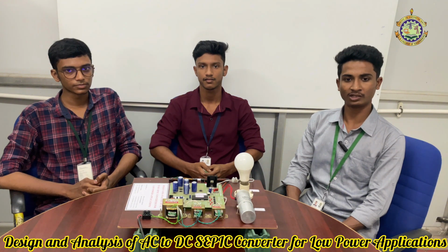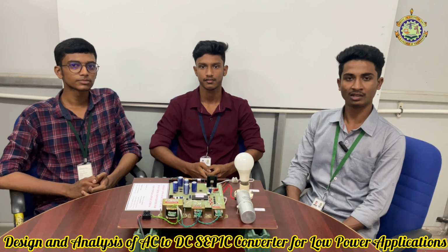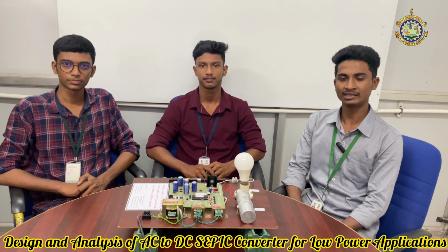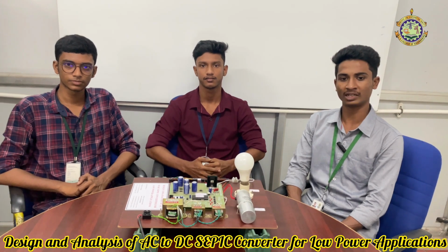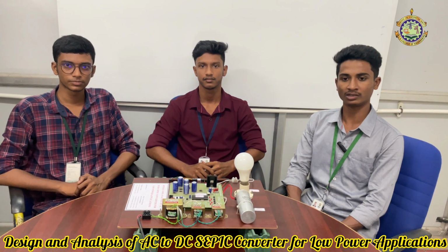Using a SEPIC topology operating in discontinuous conduction mode (DCM), this allows for natural power factor correction and drastically reduces the total harmonic distortion, helping us comply with the IEC 61000-3-2 Class C power quality standard. The system is designed for a 15 watt LED driver with 230 volt AC input and 15 volt DC output